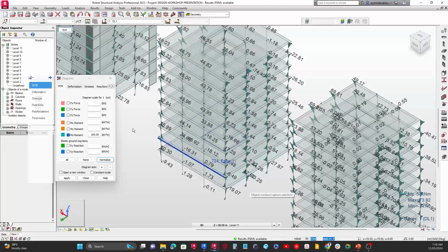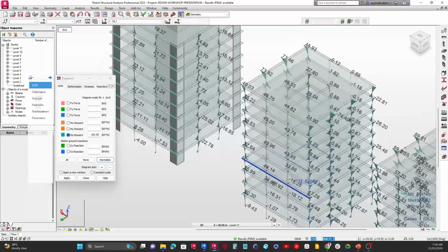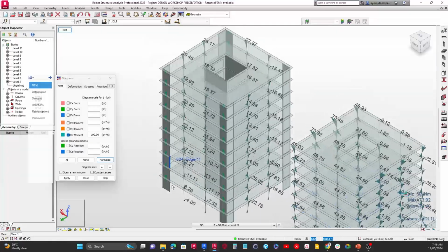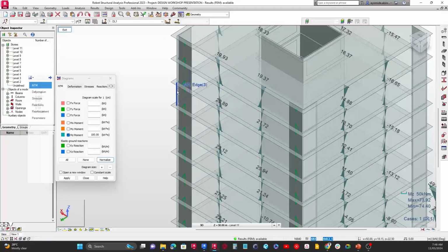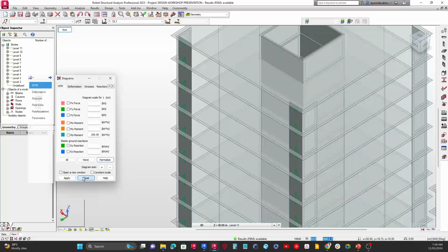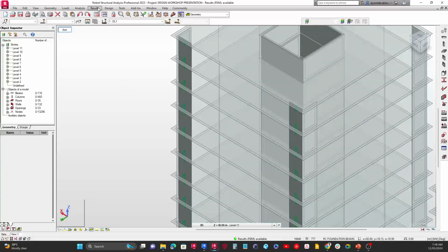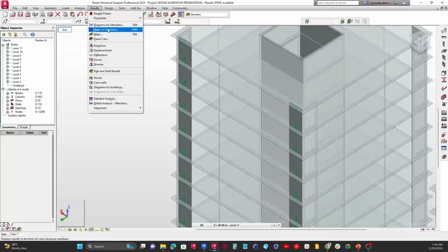All right, now let's go and do something else. So we looked at the axial forces of columns, but at the same time as well, we need to also look at the forces being transferred from the walls all the way down, because basically walls also do the same things as columns in sending the loads, apart from resisting the lateral loads like winds and seismic loads. They also transfer the loads from the floors to the foundation. Now we check that one in a different way, and how they send the loads is quite different from columns because they distribute it over an area. So let me go ahead and check.